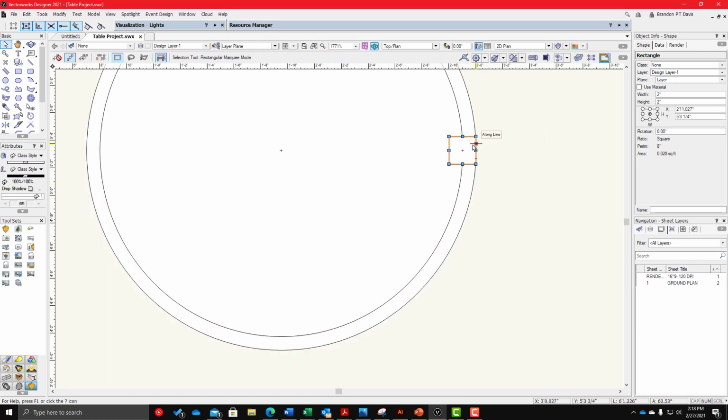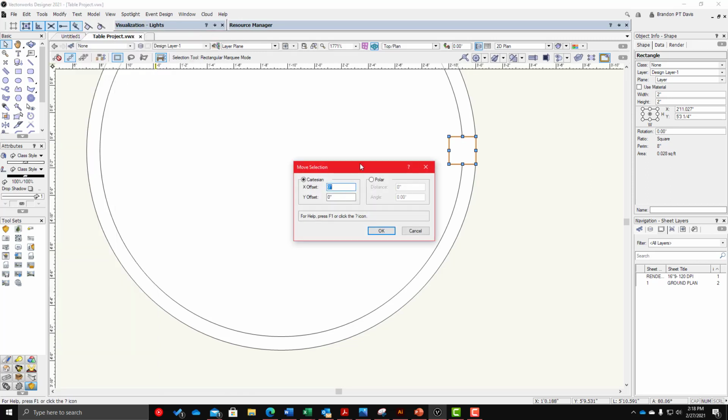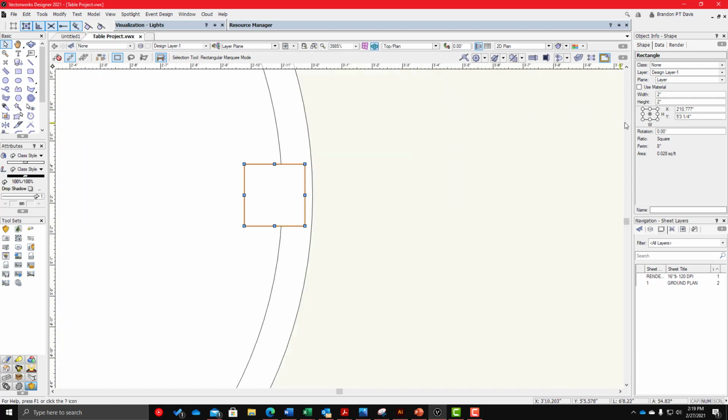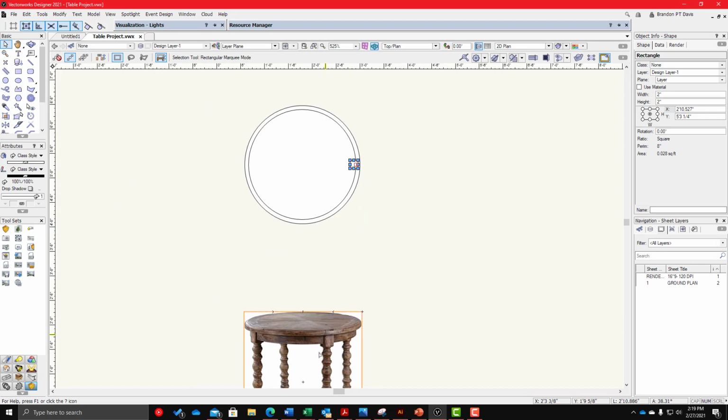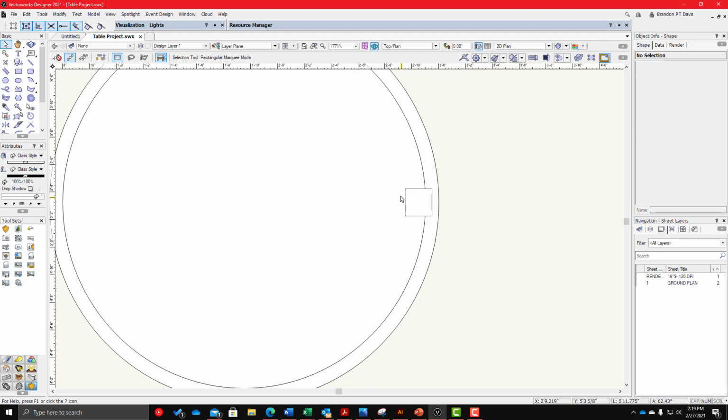So what I'm going to do is hit Control or Command M. Sometimes the software to record and the software to use don't play well together. So that's the move tool. Control M, and I'm going to offset this by, let's try 1/4 inch. You can also come over here and just adjust the x-axis. So maybe it's a 1/2 inch inset. I think we're going to try 1/2 inch inset first. I think that probably looks about right.